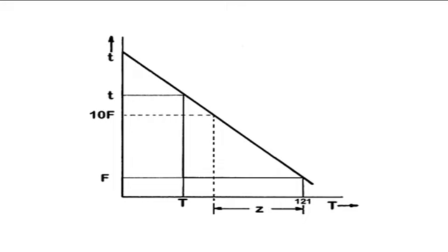The D value of an organism is the time required in a given medium at a given temperature for a 10-fold reduction in the number of organisms, and the Z value is a measure of the change of the D value with varying temperatures. It is possible to choose values of F and Z to suit specific requirements based on contaminating organisms. Basically, heat treatment can be classified into 3 categories.